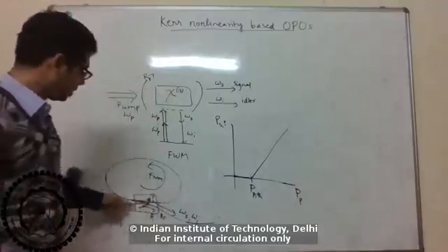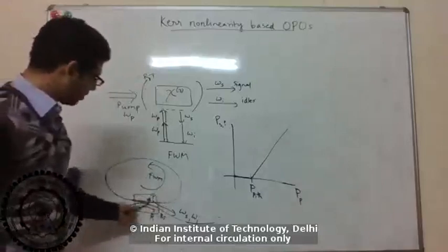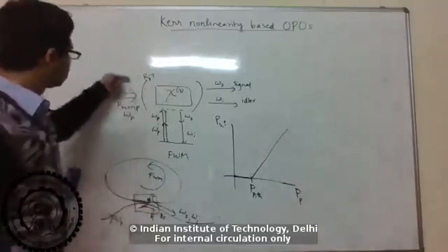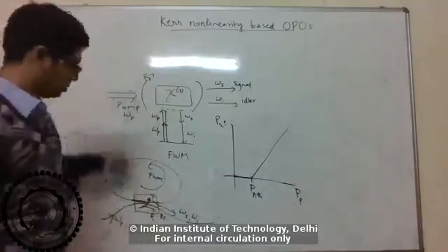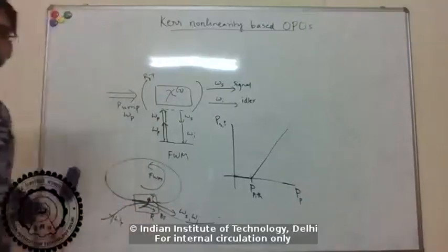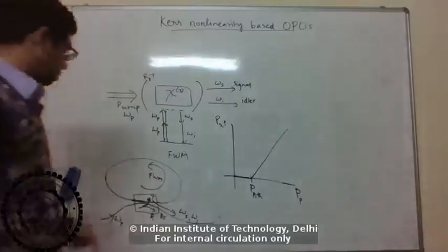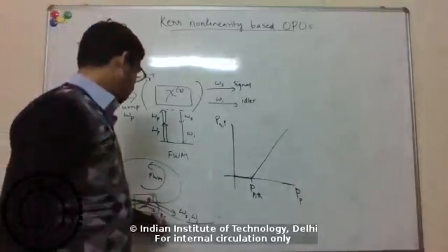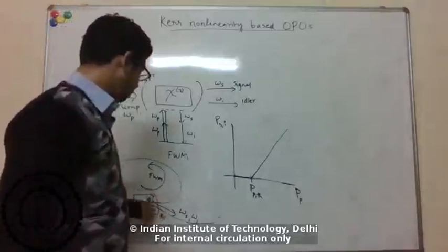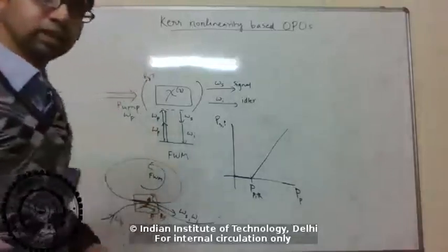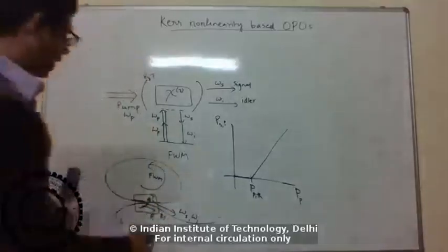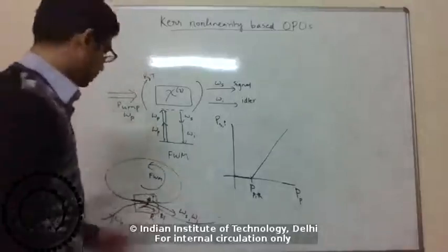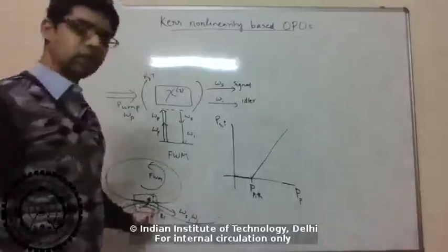That's the transmission coefficient. And the part which just stays out is the reflection which comes back. So you can think of this coupling region also as like a mirror or a beam splitter with some reflectivity and transmittivity, where again R plus T is 1, if this region is lossless.